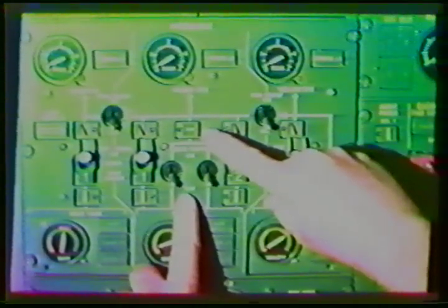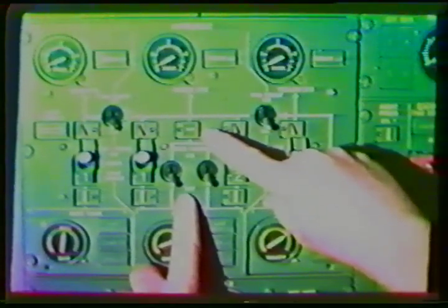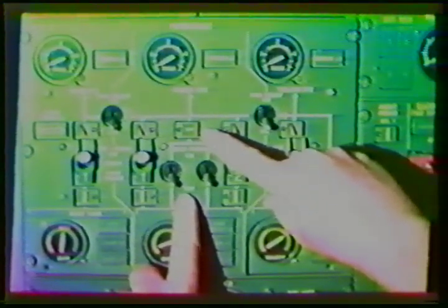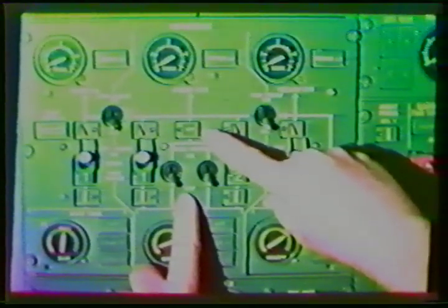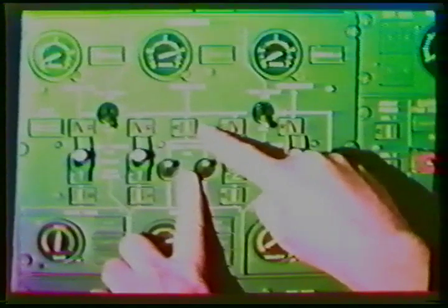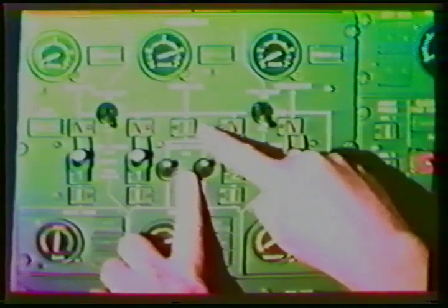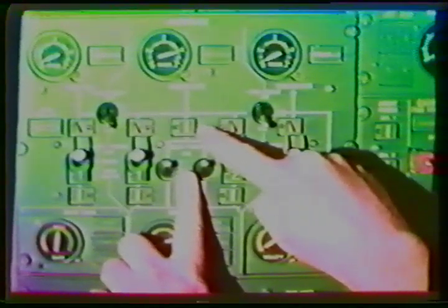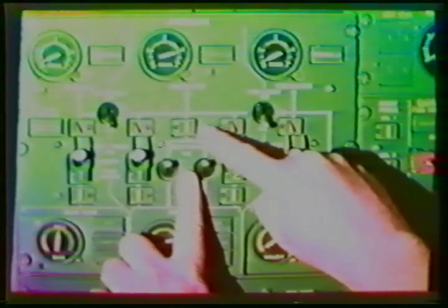One magnetic indicator monitors the outlet pressure of the pumps. The MI will be cross-line until one or both pumps are turned on. Then the MI should go in line. The flow rate of the electric pumps is reduced from that of the engine-driven pumps, and they are used primarily for ground test operations.